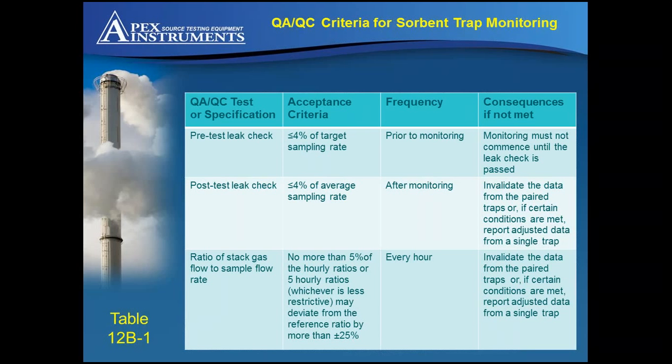The ratio of stack and sample gas we talked a little bit about already. It must be that no more than 5% of those 1 hour periods can fail, and all of those have to be within 25% of the original hour reference period.